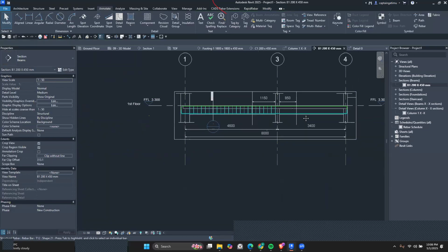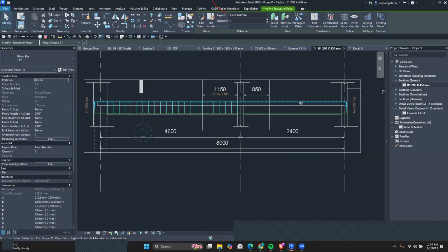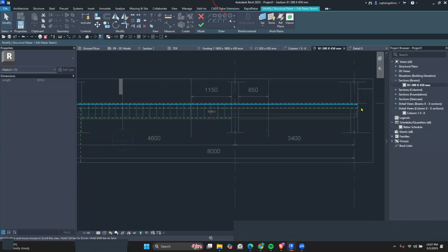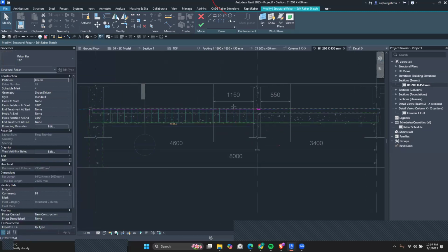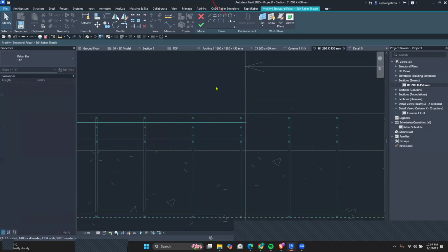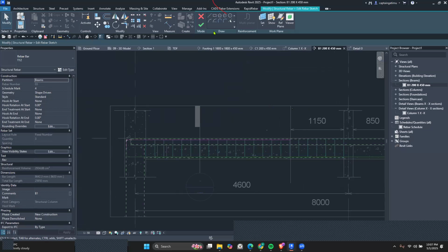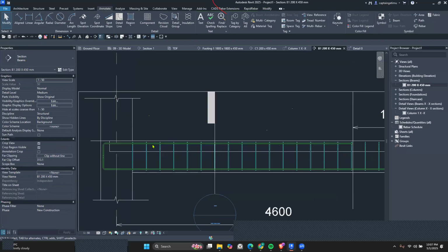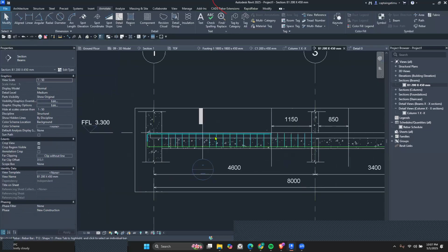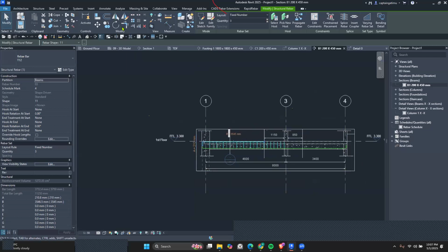Okay, and then after you have that, now we can make a few changes here. So let's edit the sketch. For this one, let this bar end at that point. Okay, and then click on finish. Select this bar. You would like to change the comment to probably top one. And then finish that. Then select this other bar.